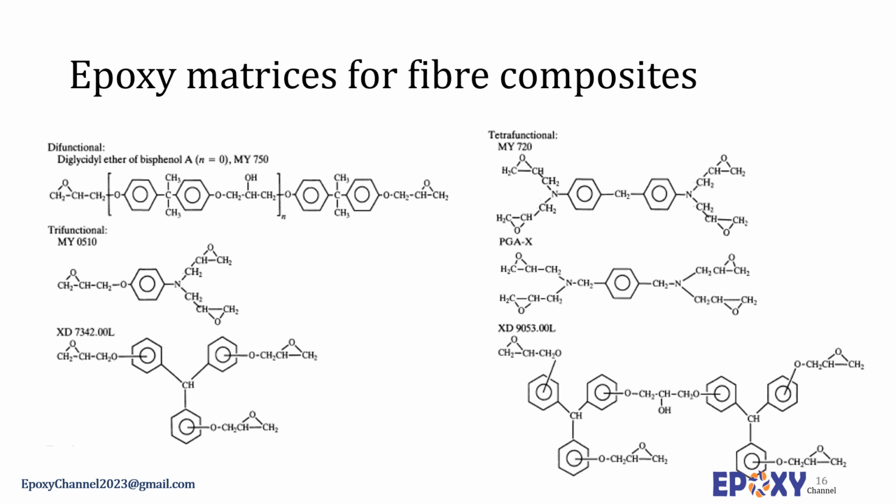The choice of the resin and hardener determines the cure procedure and the viscosity profile during cure. Other modifiers, for example, polyether sulfone and phenoxy resins are also used to control process variables. Moisture absorption leads to a significant reduction in glass transition temperature of the cured resins, which seriously limits the maximum service temperature. To mitigate this effect, highly cross-linked resins with the incorporation of the toughening modifiers are required. The thermoplastic modifiers can also be used.